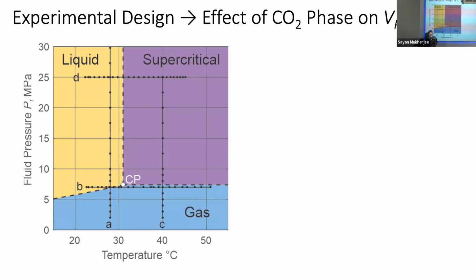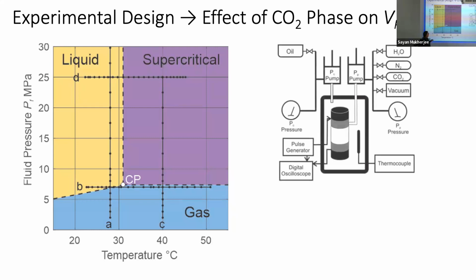Now, the experiment looks simple. It was actually pretty challenging. There'd be our core sample. We build our own transducers, in this way that you saw yesterday. There's a pressure vessel here, and thermocouples to measure temperature. Basically, we pulse the transducer on one side, we get a wave coming through, we pick it up here, the P or the S, and measure the waveforms, and we interpret those. We control the pore fluid pressure, and we control the confining pressure on the sample.